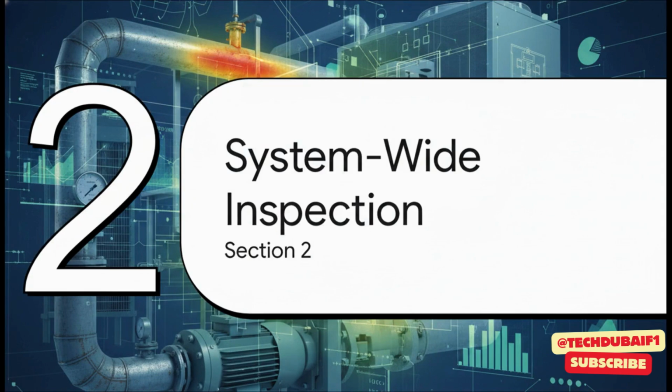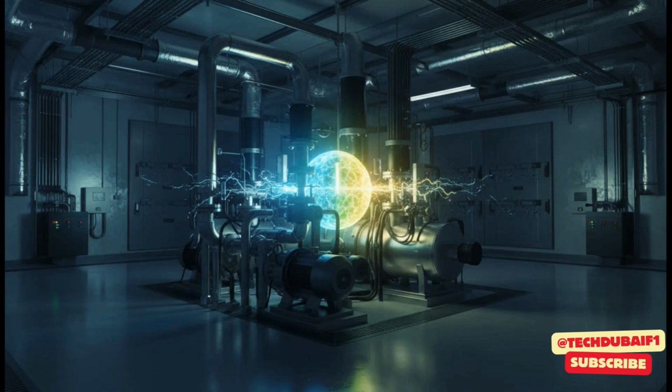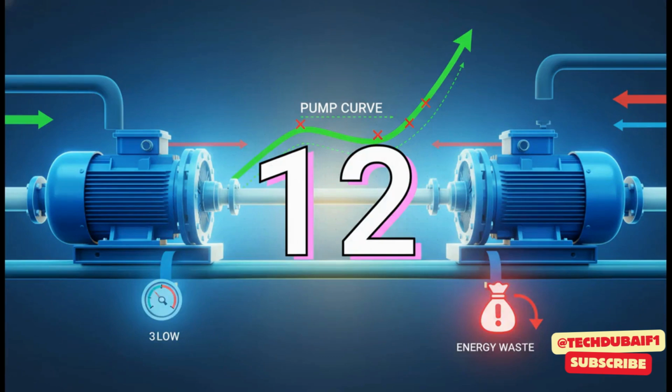Okay, so once the data has pointed you in the right direction, it's time to get your hands dirty. This is where the investigation moves from charts and spreadsheets into the real world of pipes, pumps, and machinery. The physical search starts right at the source, deep in the mechanical heart of each zone, the energy transfer station rooms. Think of these as the central hubs where all the chilled water is managed and sent out. You know, if there's a problem at the very core of the system, it's going to affect everything else down the line. First up for inspection are the big guys, the primary pumps.